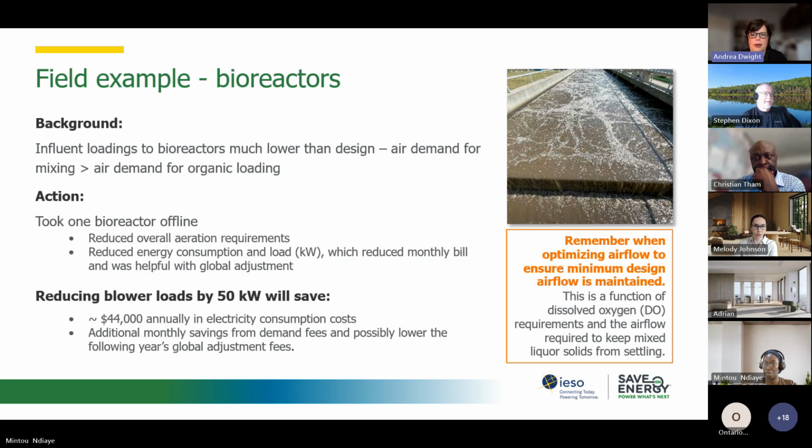So actually, Andrea, on that point, what I always like to keep in mind is that 1 kilowatt off the 5 top peaks is worth anywhere from $300 to $500, minimum $300. So 50 kilowatts off all 5 top peaks could be worth $15,000. So that increases that opportunity significantly.